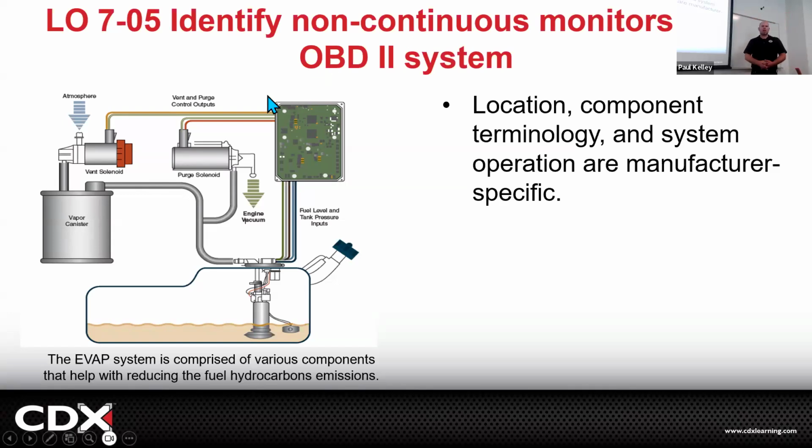So instead, she brought it to the shop. The shop checked it, and it was a P0455, I believe. There are several different codes that could be set. It was for a gross leak, a fuel evaporative emissions large leak or gross leak. That means the whole system is leaking. It won't even slightly hold any vacuum or pressure. So the technician pops open the little gas door on the Civic, where you release the latch, and there is no gas cap. She left the gas cap at the gas station.